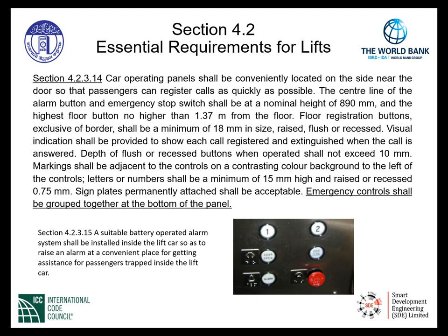And last, emergency control shall be grouped together at the bottom of the panel. As seen in the picture below, we have the emergency controls indicated together at the bottom of the panel. The left button is an alarm button down at the lower left-hand portion of the picture, and on the right-hand side, adjacent to the alarm button, is the emergency stop button.